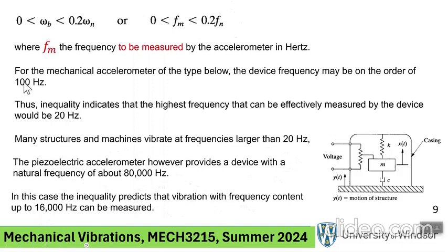That's very good. Instead of 0 to 20, you can measure between 0 and 16,000 hertz, as long as you pay a price: go to a new technology, new material, piezoelectric ceramics, and replace K and C with that ceramic block.